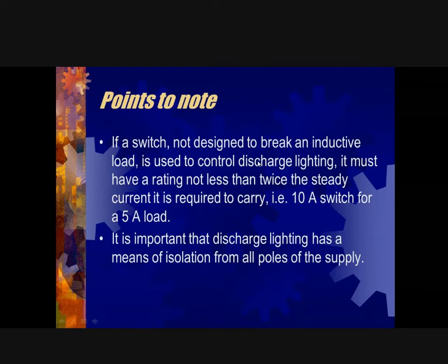Because of the initial inrush current, which we know will be present based on the type of discharge lighting we're using. Before it gets to steady state, we're going to have a sudden inrush, and then the choke will take effect, and then it will start to reach your constant steady state, right?